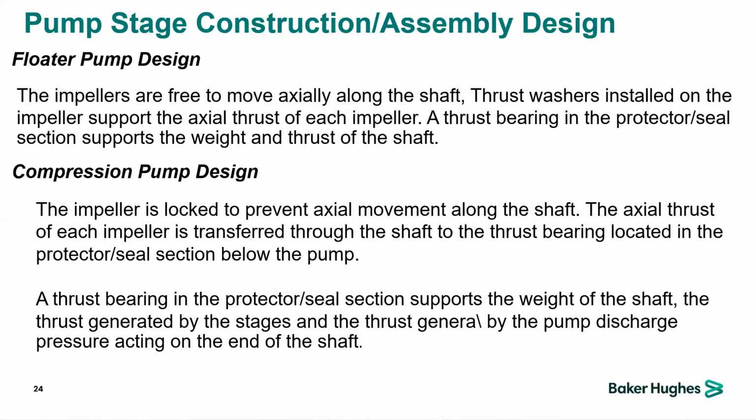So the bottom line for any selection is to go to floater and don't complicate your design, and go to compression unless you really need to, because compression will be better at handling sand and better at handling gas, because the impeller will not sit on the diffuser and it will not easily be plugged or stuck with the sand in the compression pump design.